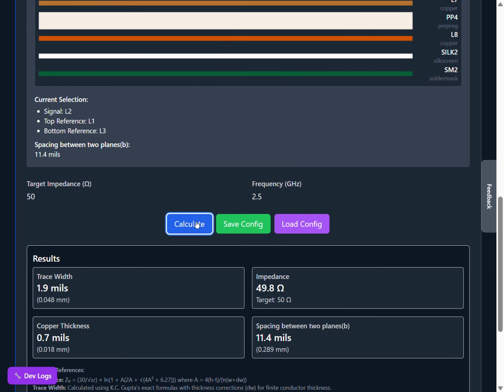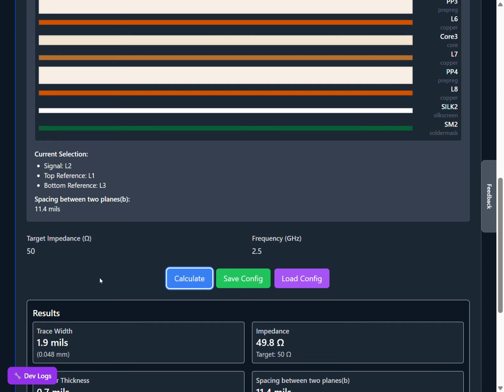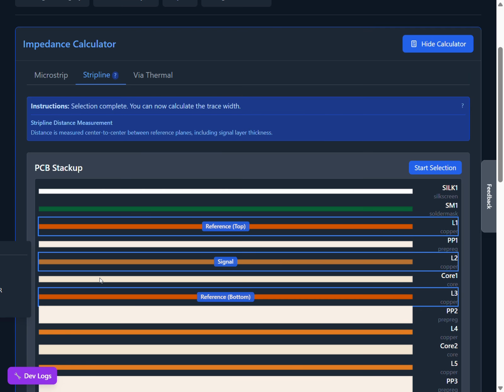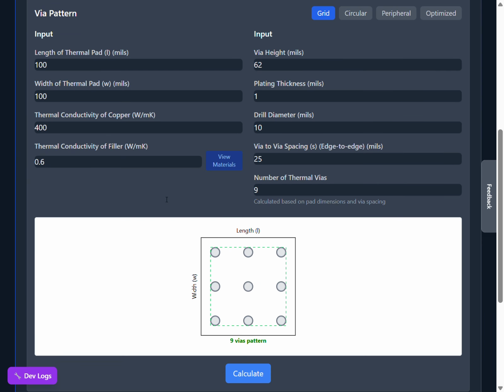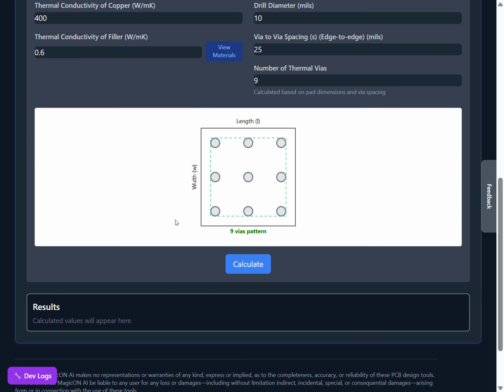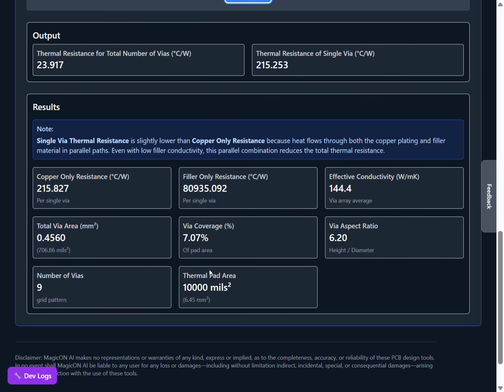Pros: easy access for probing and tuning, wider traces for the same impedance, can have lower conductor loss in many cases, geometry and frequency matter. Simpler stackup, you only need one reference plane, and better thermal dissipation. Surface traces radiate heat to air. Stripline is trapped in the dielectric thermal blanket.